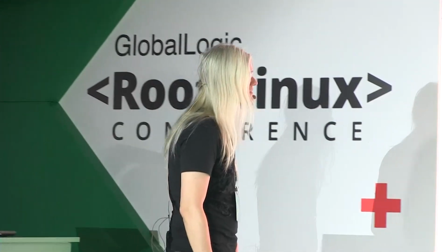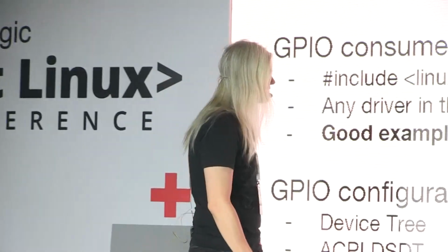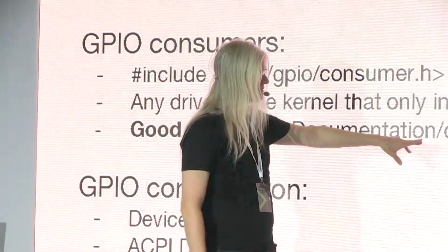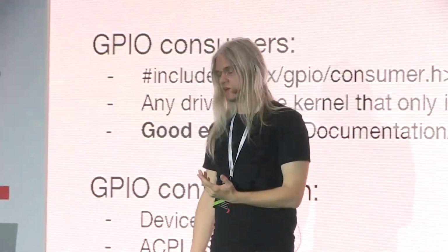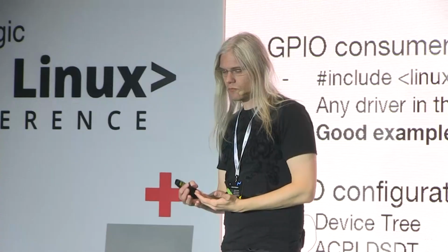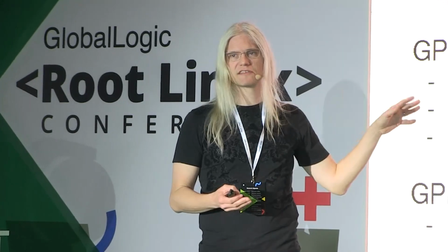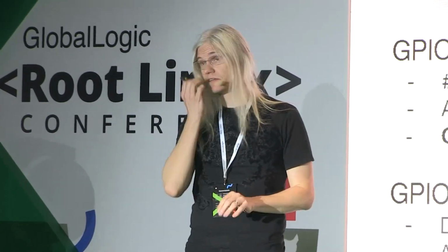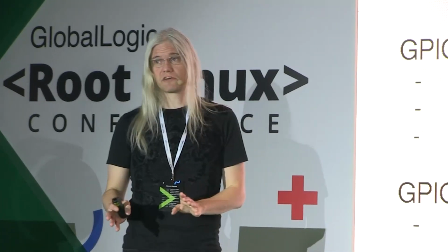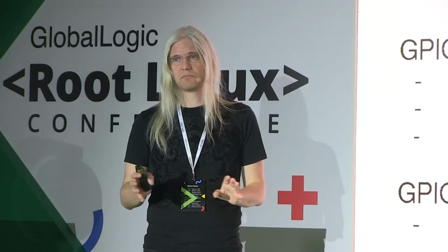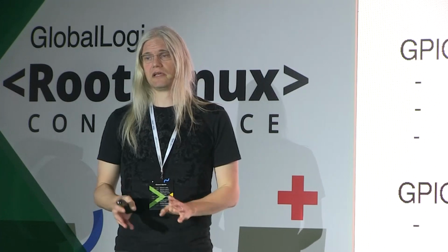If you have a generic use case that you want to do, like an LED or a switch or a connector of some kind, then look in this directory, drivers/gpio, because there's a high probability that what you want to do, somebody else has already done. Like the bit banging things that I mentioned. Somebody has already done that. Use those drivers. Don't reinvent them. I've seen so many vendor kernels where people have reinvented the GPIO wheel so many times.